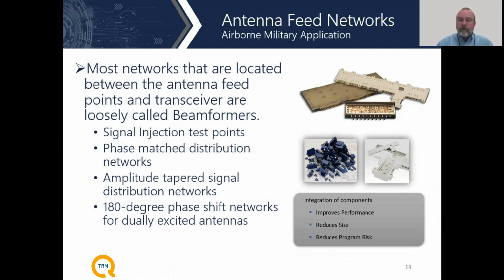Very often these are used as signal injection test points. A lot of these systems, you want to be able to make sure that you can calibrate out, for example, phase differences over temperature, cable length differences that are run through the aircraft, and other sorts of things, especially if you're dealing with interferometer-based systems where phase relationships between elements are critical for determining angle of arrival.